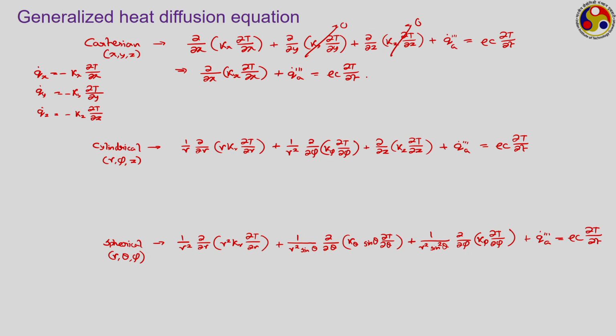And if we are talking about an even simpler case, that is steady state, when heat conduction in the x direction is significantly larger than heat conduction in the y and z direction. And along with that, if we assume it to be steady state, then what do we mean by steady state? There is no variation in time, it is equal to 0. That means any ∂/∂t quantity can be said to be equal to 0. In that case, your equation becomes even simpler.